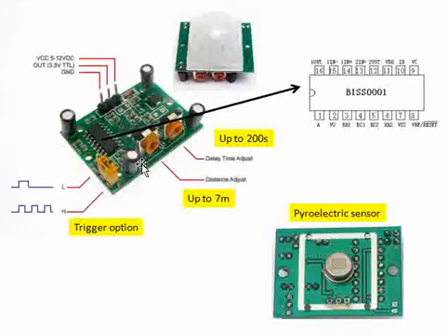And then ultimately what happens is when this sensor senses something, it will produce some output over this output rail, right? That's what we are talking about here. For example, let us assume a human is walking in front of the sensor, and initially the output is low and then there is a high that is seen on the pin once the detection happens.